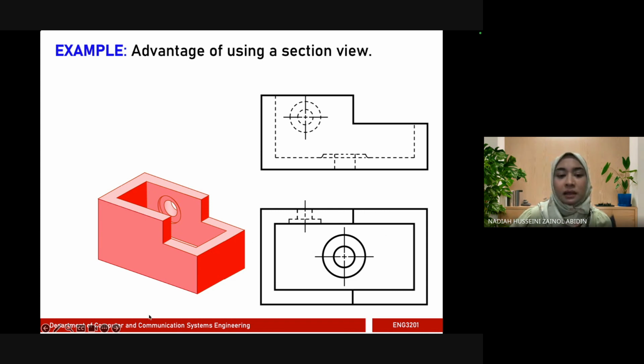Sorry, my bad. So from the front is here and then you would have hidden lines because you are observing from here. Okay, so you have this hidden line and then you have this hidden line which indicates that there is an edge inside of the object, and then you have some structure going on here, and when you view it from the top you would see that actually this structure is this guy.